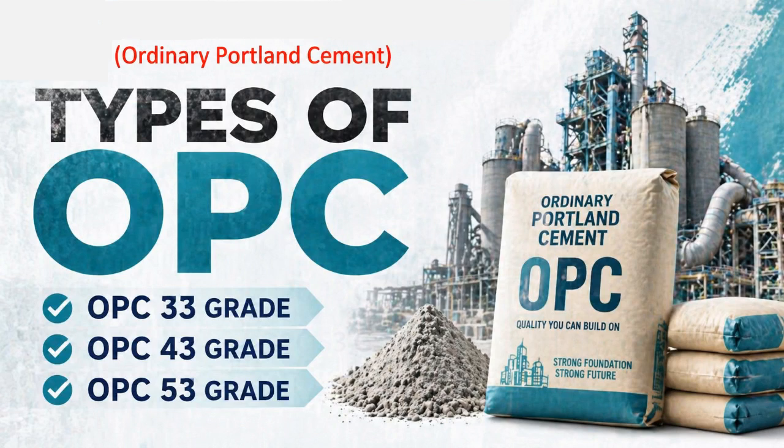And the last strength grade is OPC 53 grade. This is the highest strength grade of OPC and is used for high strength requirements like high rise buildings, bridges, highways, and heavy RCC structures. It gains strength faster compared to other grades. These grades are defined as per the Indian standard IS codes based on their compressive strength achieved after 28 days.